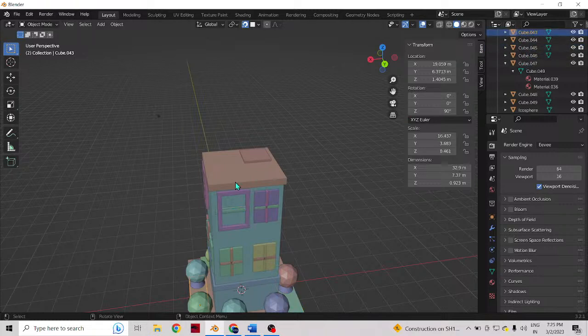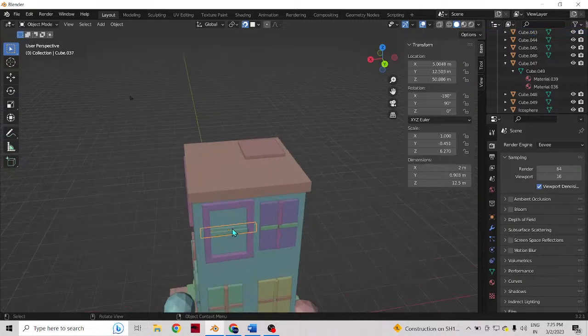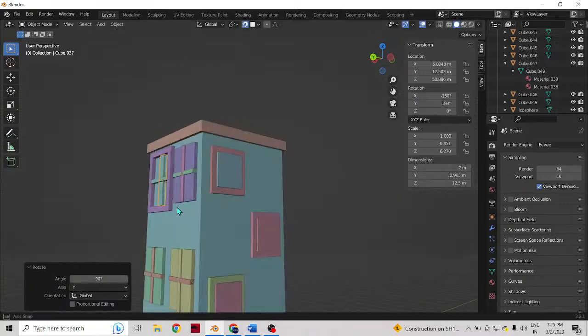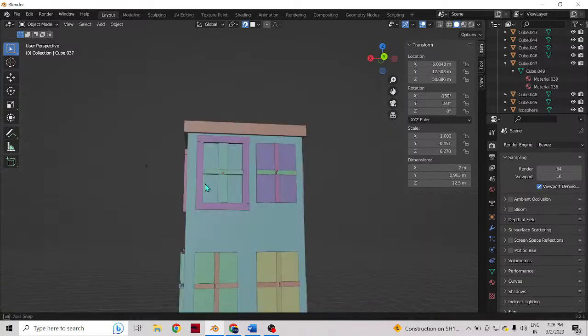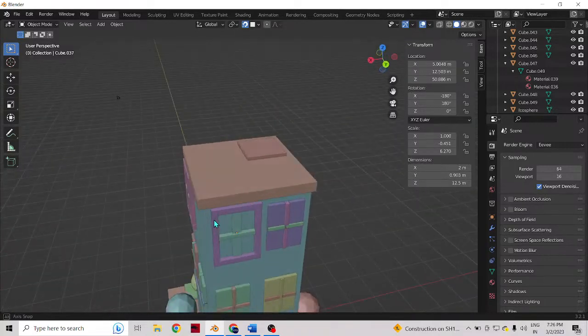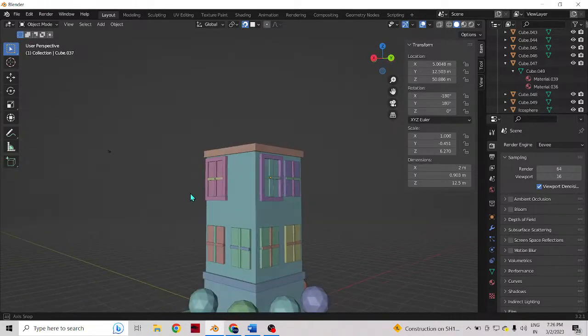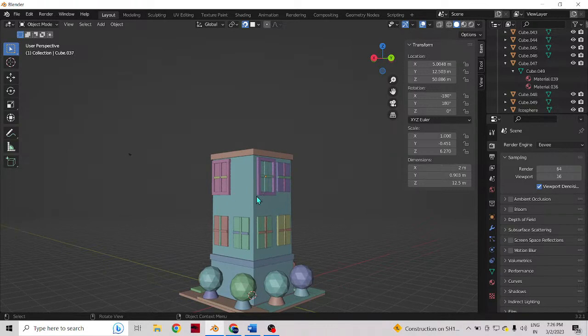Okay, I'm just going to see where the frame is. So here the frame is like this. Now I'm just going to rotate it in Y and fix it in 90-degree. Okay. So this method is applied when you want to copy an object, okay, but you want to place it in different phase.